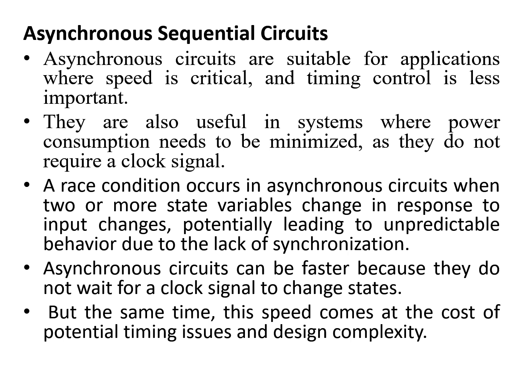A race condition can still occur in asynchronous circuits when two or more state variables change in response to the input changes, potentially leading to unpredictable behavior due to the lack of synchronization between them. Asynchronous circuits can be faster because they do not wait for a clock signal to change state. But at the same time, the speed comes at the cost of some potential timing issues as well as design complexity.